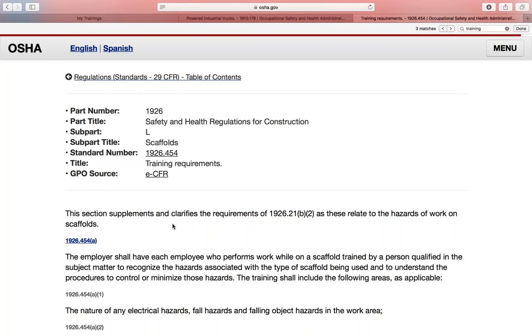Okay, so what do we have to do? Avoid using the lift outdoors in stormy weather or in strong winds. Why? We want to be cautious of hazards related to lightning, and then also wind. Possible tipping or maybe pushing us into energized components or whatever the case may be, or other hazards. Also, prevent people from walking beneath the work area of the platform. No one should be underneath that platform, and if for any reason anybody is required to go under it, my recommendation is always to be brief and to use a spotter.